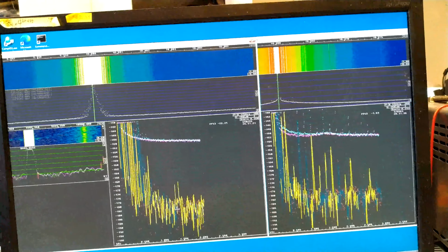And further, the red dots are at the same level, and that is the signal in quadrature, the signal that is 90 degrees from the expected noise of the amplifier. So this setup shows that my system is not capable of measuring better than about minus 180 up here somewhere, maybe even minus 178. And it's the same for both systems, although I don't see as many blue regions for the sound card.